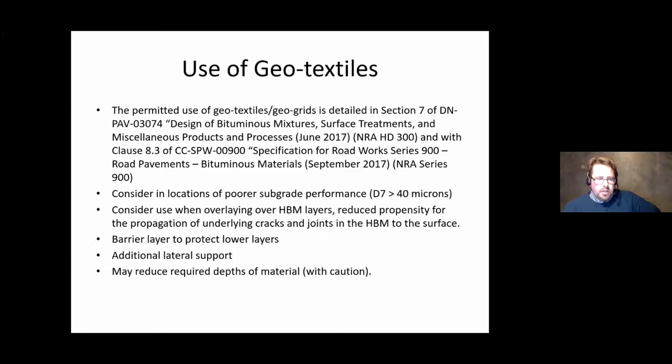They'll reduce the loading, they'll spread the load much better, so you're reducing the load in your subgrade. They also reduce the propensity of the pavement to settle differentially. And if you're overlaying on a bog road or bog rampart, the peat material has a propensity to settle differentially under its own right. So you need to be conscious there that if the pavement is settling, you don't want to be increasing the pavement thickness more than you have to. So you could potentially be better off inlaying and including a geotextile to incorporate it, or if you do have to overlay, keep it to a minimum and incorporate a geotextile there just to spread the load.